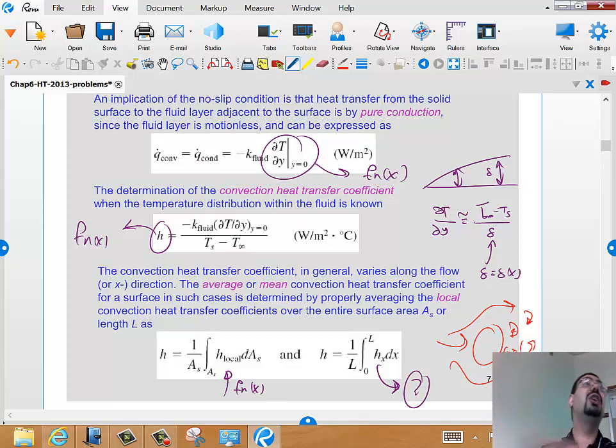All right? Even natural convection, when there is just a hot plate and the air is rising because of the heat, it will not really be the Reynolds number, but it will be the same concept. Some kind of a number that tells us how quickly the air is moving, multiplied by a Prandtl number. That's the essence of convection. You make the air move, and it takes the heat with it. So it's a Reynolds number multiplied by a Prandtl number. All right?